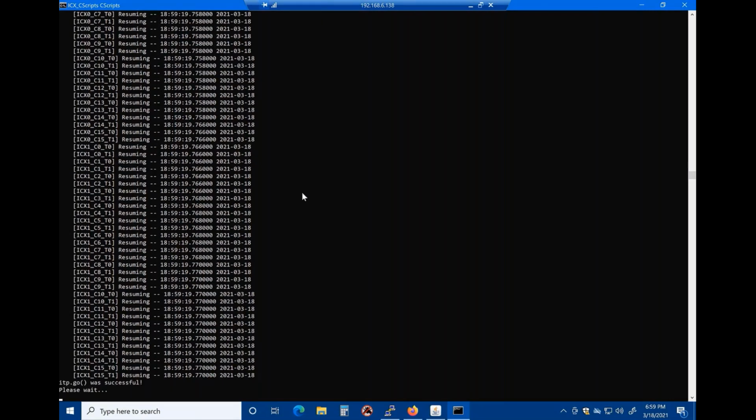So crash dump, the first thing it does is it puts the platform back into a running state, and then you can see down at the bottom, I'm going to speed this up as well because we're not going to sit on this webinar all day. It goes out and collects the register information on the bits of IP within the Intel CPU that it's interested in. The first thing it does is go out to each and every core and extract a bunch of register information for all the associated sockets, cores, and threads.